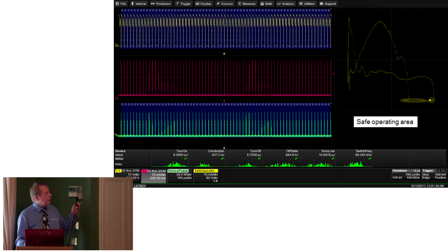This kind of thing, we think about doing this measurement, okay, it's straightforward to do, but if you're making a switching power supply, you need to think, well, actually it's got to work from what? From 85 volts to 270 volts. Because it's got to work in Japan, it's got to work in the UK, it's got to work in the US, so it needs a wide range, and it also has to work under different load conditions. So when measuring these, obviously you need to measure it with different input voltages, but also different loads, full load to low load across all those voltage ranges. But that's just a little bit on power.